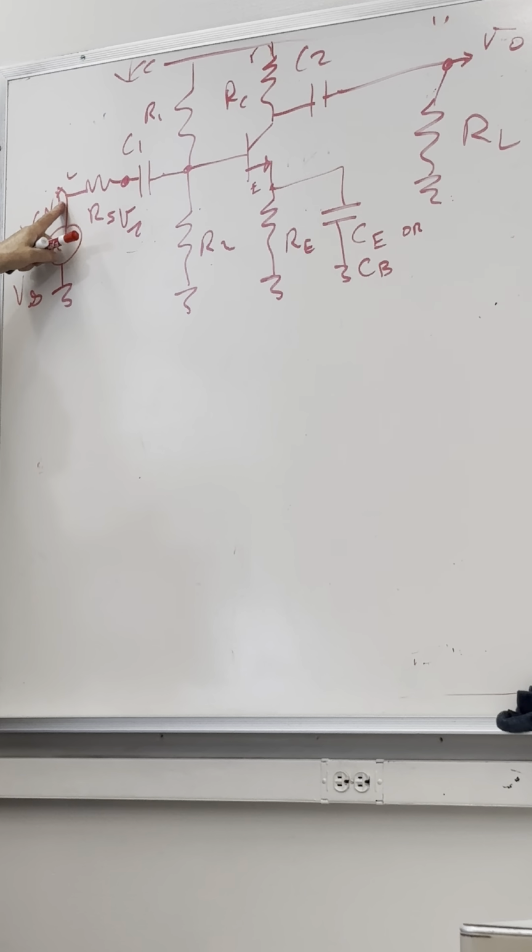You will put all the DC voltages to short, all the DC voltages that exist in the circuit, and the capacitors into short. So all capacitors short, all DC voltages short. They are not moving, they are zeros. So here, this is not short because it's fluctuating, it's a signal. So you start here, that's the signal.